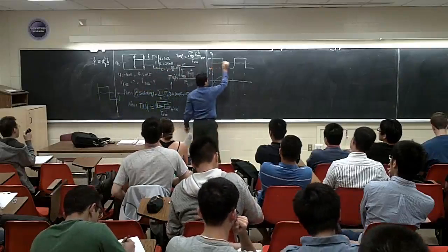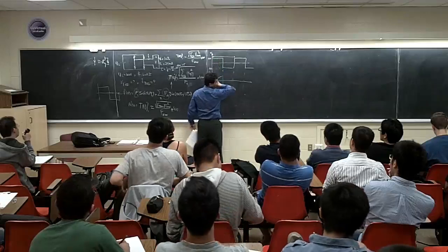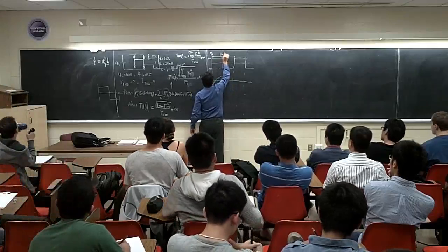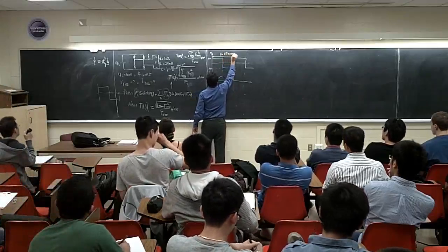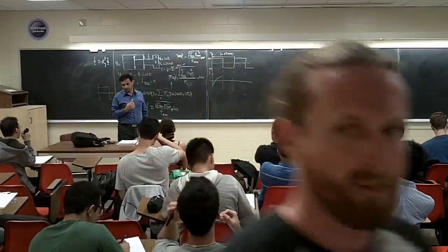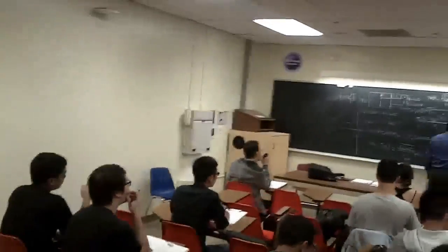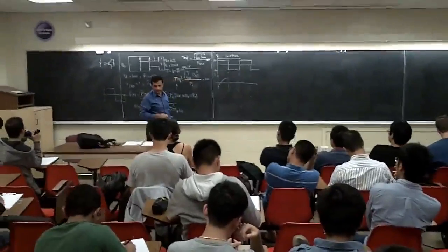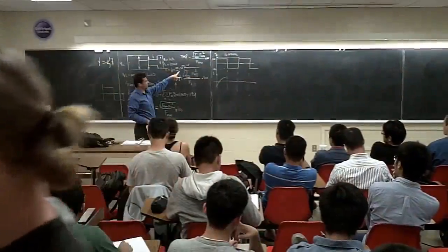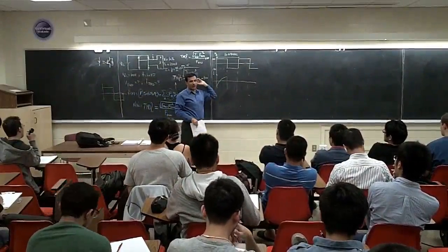That's 2.5 millisecond. From here to here is how much? This is a 60 hertz system, right? How much is that? 16.67 milliseconds because that's a 60 hertz waveform. So how much is this one? This is almost half. This is 8 milliseconds or 8.5, something like that. Now compare with this one. How much is this one? 2.5. That one is 8. It's maybe 3 times, right?